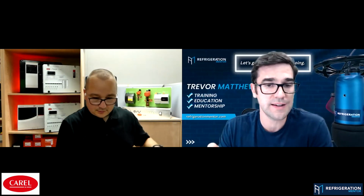So most refrigeration technicians, we're not welders, right? We braze and stuff. So we would have to actually cut that out if you cannot take it apart. So this valve is one that you can take apart. Cool. Exactly. This is the good thing. It's a demountable valve. It's one of our smart valves. So you can simply exchange the whole thing, and you can leave the body inside of your application. That's the easy part. So they replaced it, and this is how it looks.